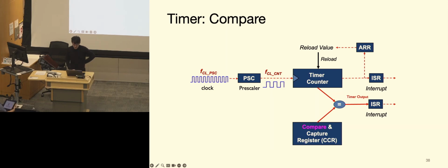And also, when the timer is configured to generate the output signal, the hardware will consistently compare the counter with the value stored in this CCR. Whenever they match, it outputs something through GPIO pins or similar, and has some event triggered by that timer.